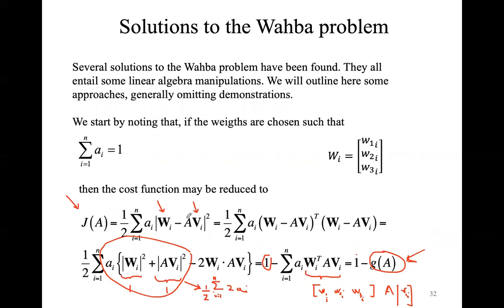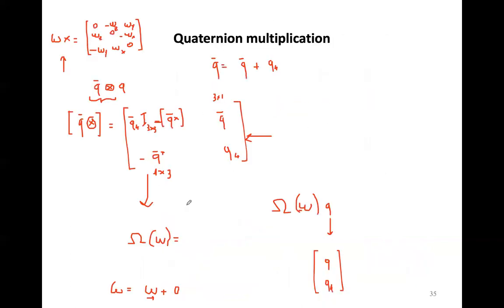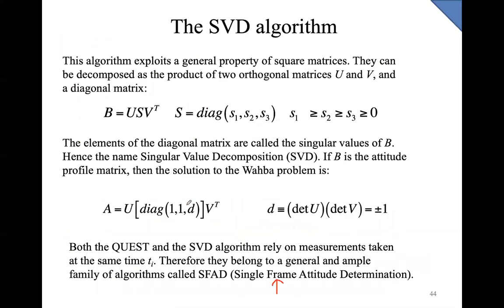By rotating these two versors to the optical bench frame, you're able to get this versor in the body frame. So what you need to know is the attitude. You have these two versors that have to be compared in a certain way in order to provide the attitude of the spacecraft. So the star catalog gives you V, and W is given by the sensor.